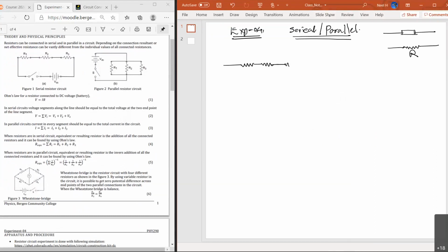In this experiment, we're going to take 3 different resistors, let's say R1, R2, R3, and we're going to connect them serially. And there should be a switch, and I should have a power supply, like the battery. So I have a battery voltage. Usually we write VDC, or sometimes you will see just the E symbol to represent the battery. Switch is S. When you close the switch, the continuous loop will be set up. As a result, the current will pass through this loop, right? If I have a serial circuit, the same current passes through every resistor.